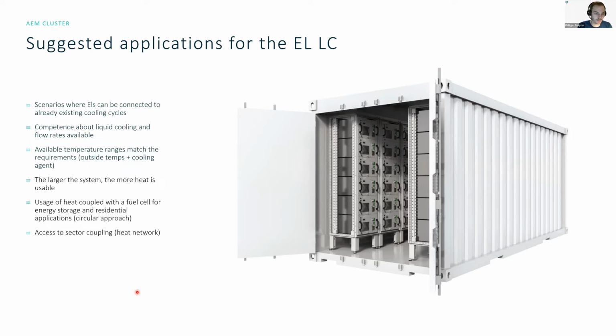Also, you should have some competence about liquid cooling and flow rates in your company. Available temperature ranges should match the requirements. So it also depends on which climate zone you're erecting your stacks and your container in. And please, as I already said, be aware of cooling and freezing temperatures.